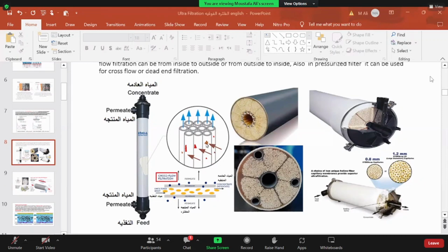But in the case of large particulates or clay particles on the membrane itself, or in the raw water itself, they will start to precipitate and accumulate, forming a cake layer. So it is better to use the technique where I have a space and the ability to remove the particulate or the cake formed on the membrane surface. In such a case, I recommend using outside-to-inside flow.